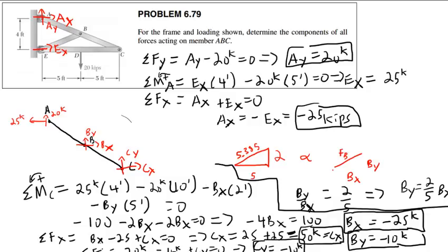Yes. So on this member ABC, the BY and the BX had the components of each individual force for a point. Isn't that the same as FBE, the force along the member? Yes, it is, but it's still two unknowns. The question was, isn't this sort of like a single force? In the same way, yes, it's just two different ways of expressing the same thing. We could say this is a CX and a CY, or we could say it's a force and an angle. In both cases, it's still two unknowns.